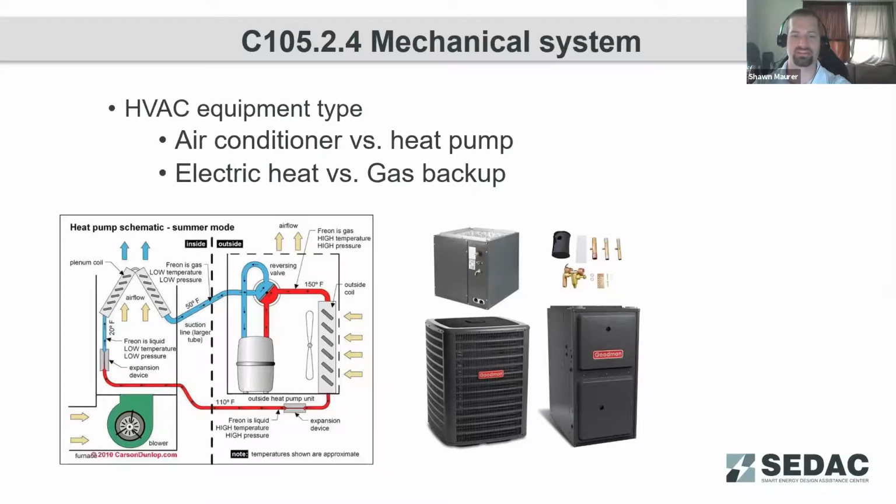Another thing is that those systems will have to have some kind of electric or gas backup system. The controls for that gas backup or electric backup system need to be verified that they're not going to be kicking on when the compressor can handle the loads in the building. They're only going to kick on when those loads exceed what the compressor can handle for heating.